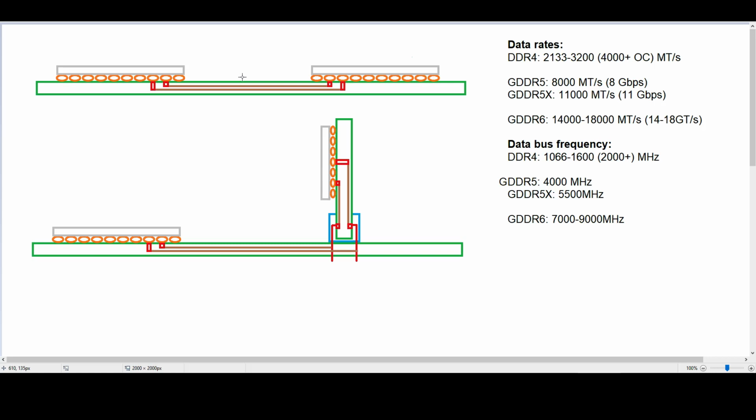And so basically, it's just too difficult in terms of signal integrity, and that's the core reason why we don't see modules for GDDR interfaces, and why I think there never will be. And actually, I wouldn't be surprised if in the future we see us moving away from memory modules the same way we have them now, because it's just very difficult to make good signal integrity when you have different interfaces like this.